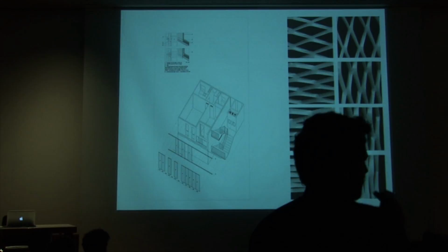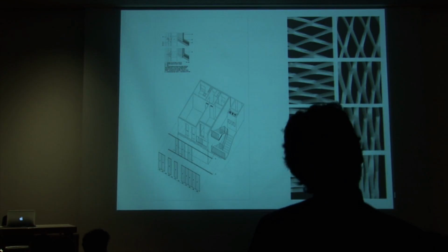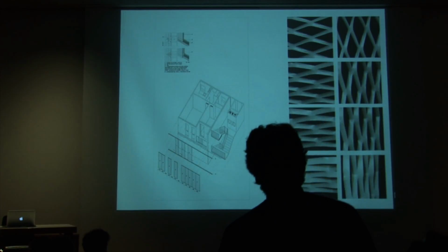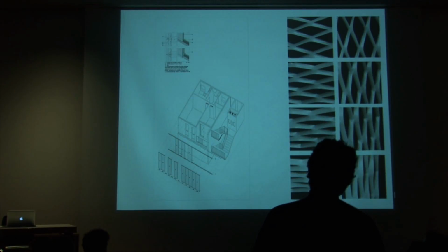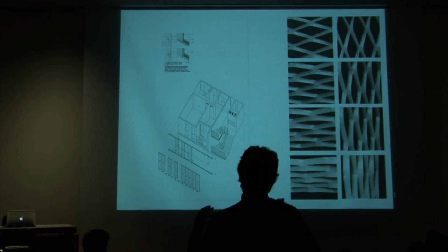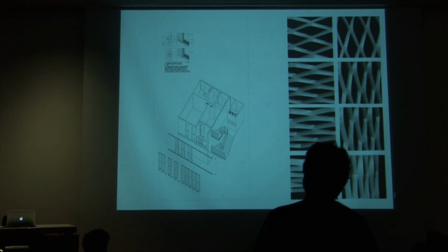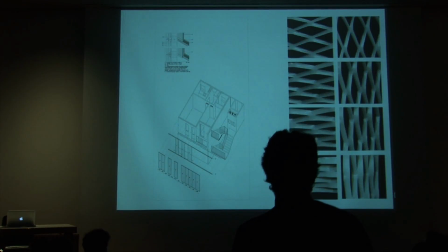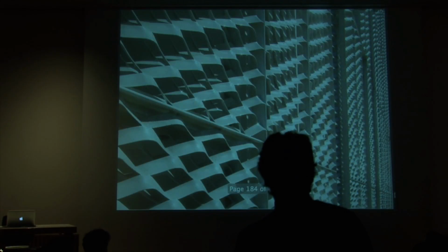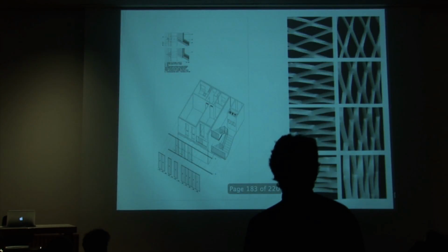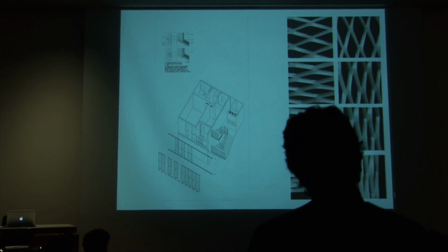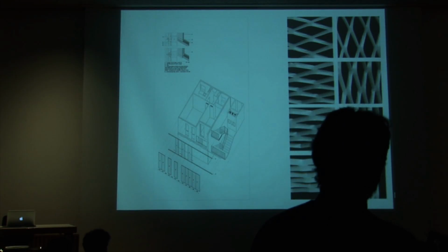As that building had too much concrete, so it was quite heavy. This massiveness could be a problem in summer because it could store a lot of heat. So we decided to protect it from direct radiation with this double facade. This double facade is placed on one facade that way to avoid summer rays and to let winter rays go through it.